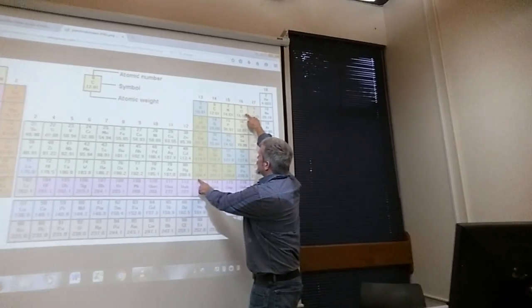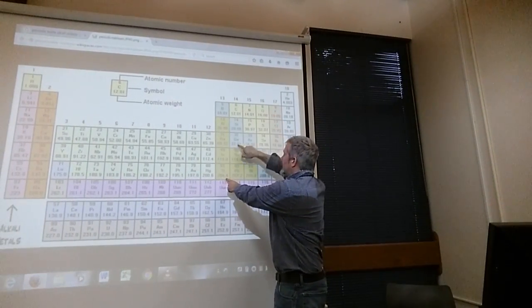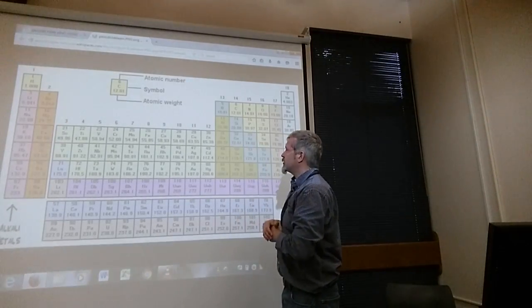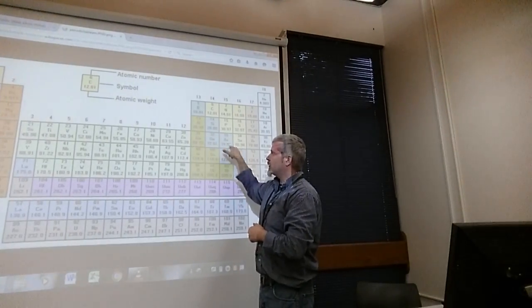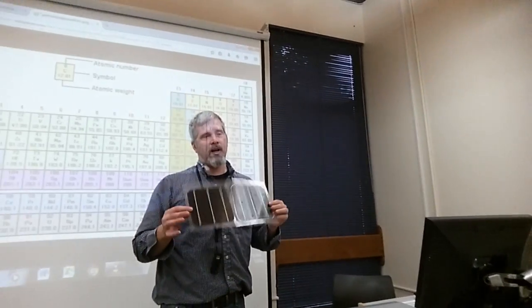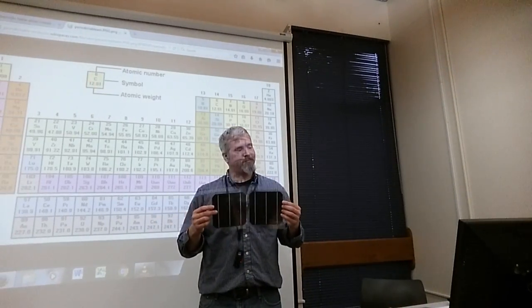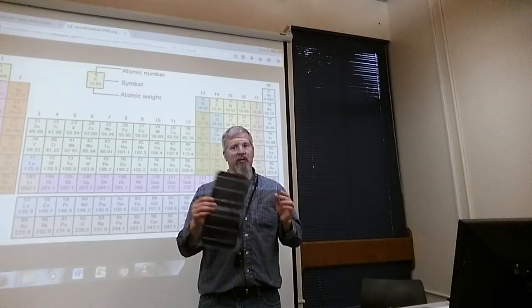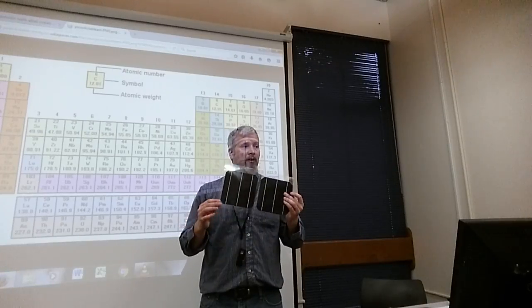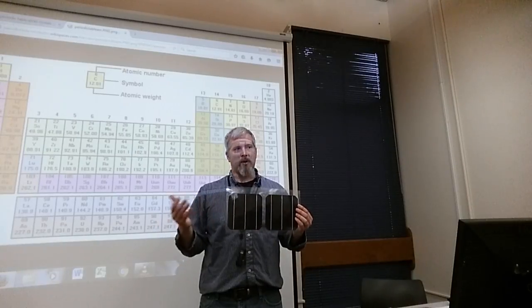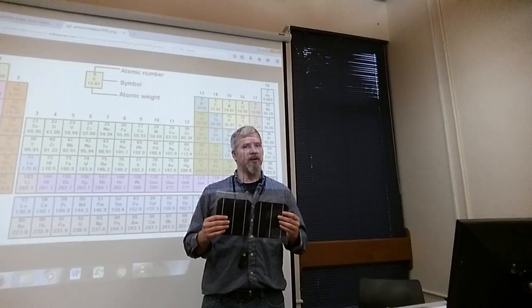So if you notice, it's still the same band that we're talking about. We have germanium, arsenic, indium, and we have gallium. So this is a different type of cell that we can create. And although these are the most popular type of cells, these are called monocrystalline cells. And so we have monocrystalline, we have polycrystalline, but they don't have to be crystalline. Like we also have thin film PV panels that work off of similar chemistry, but different materials.